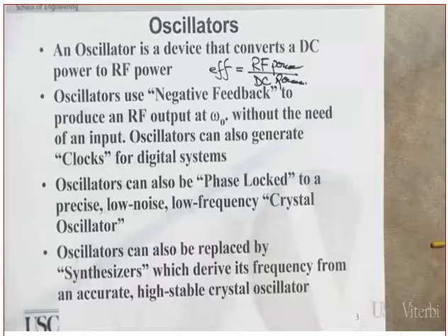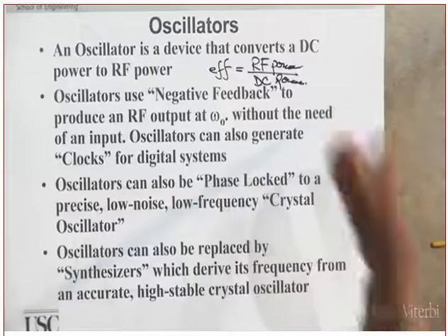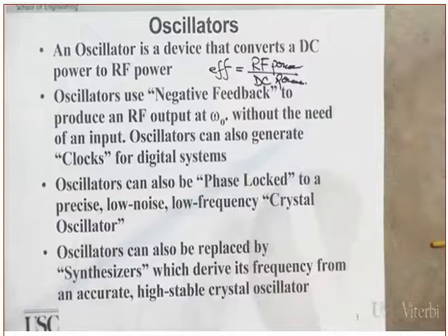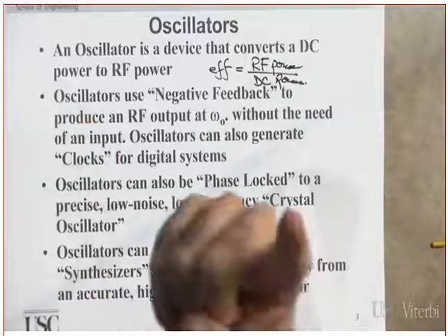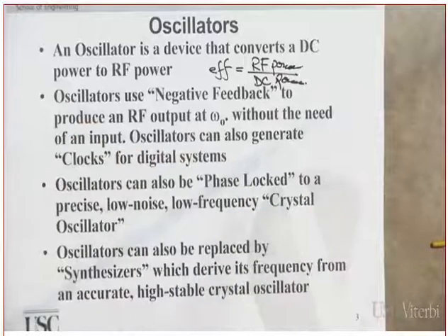Okay, but what I'm saying is that if you have taken the 477, you would know that it's called, for example, an astable multivibrator. Astable means what? Does not have a stable state. It will switch from what? 1, 0, 1, 0, or 1 and minus 1, and so on and so forth. Sometimes you will generate what is known as a ring oscillator.